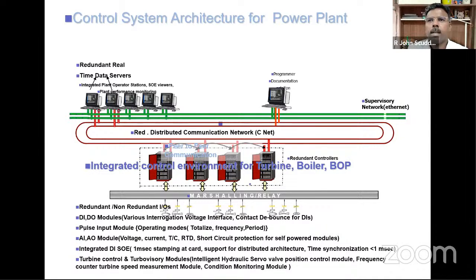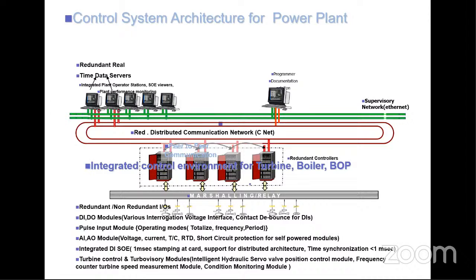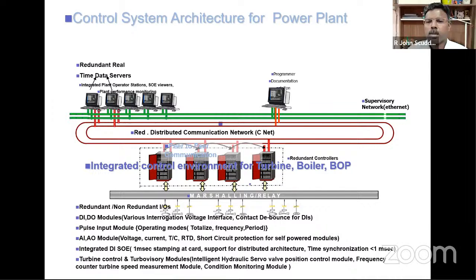For a turbine, tripping means you will be cutting off all the steam input to the turbine. That is called turbine trip. So imagine lube oil pressure. Lube oil pressure means the oil which lubricates the turbine between the moving part and the static part. If there is no lubrication, the turbine will get drastically damaged. It can go to rubbing. It can cause fire. It can cause damage to the main shaft, which is a 150 crore equipment. So you cannot imagine that to happen.